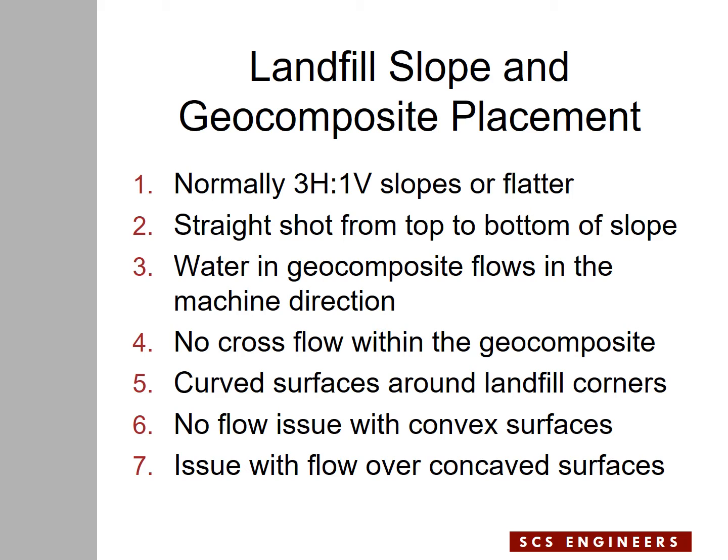But if the geometry of the landfill footprint is such that you end up with a concave surface, the geocomposite role becomes a very important matter in the design of the drainage layer for the final cover system. The drainage layer geocomposite, and sand may be in the same category as well, on concave surfaces is the subject of this presentation.